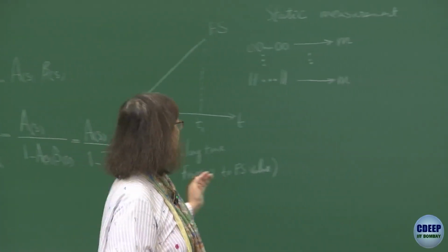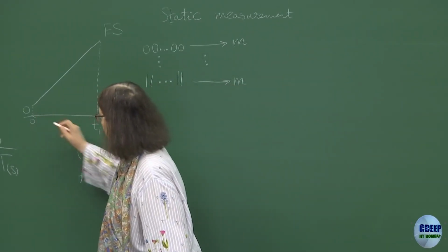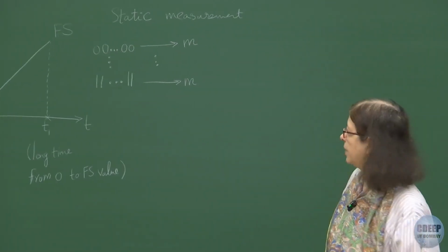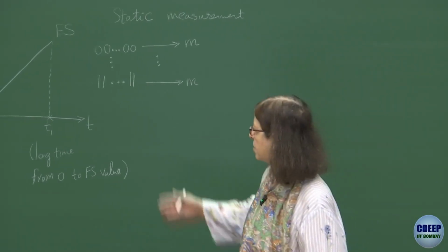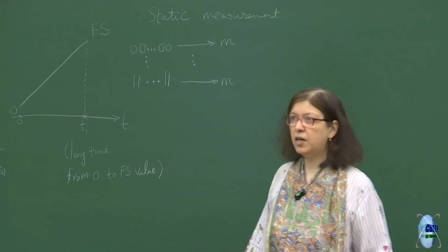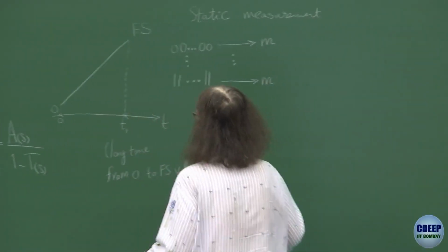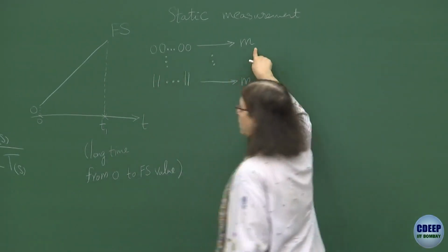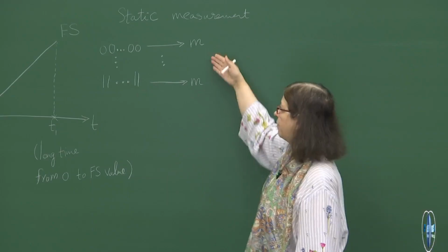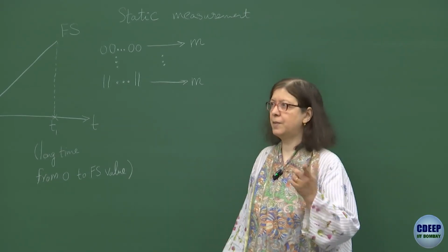So this is the whole idea, if we can control these two points very well, the initial point and the last point. This is the second bullet item. We have a very slow triangular waveform, and now it becomes triangular. It's not only just a ramp, because we may want to repeat this. Suppose I go with only one round, what would be the value of m? 1, exactly. So I will have one occurrence of each code. The histogram will still be a histogram, but the number of samples will be 1.